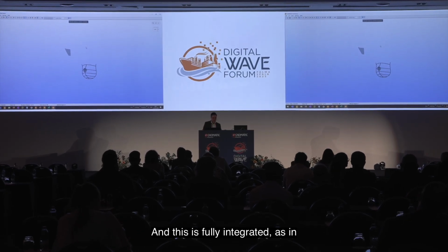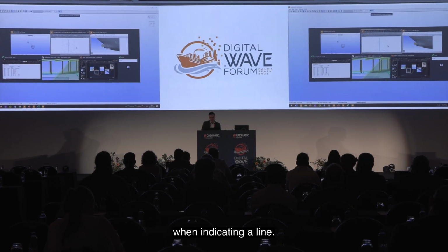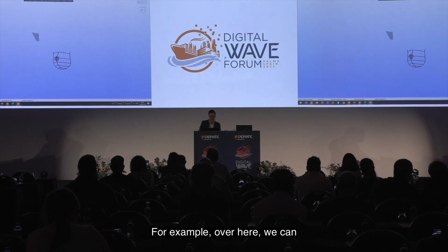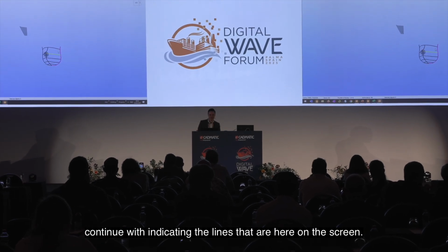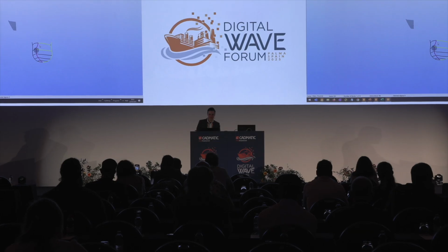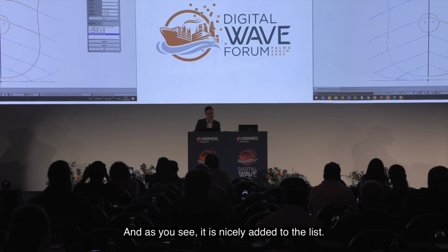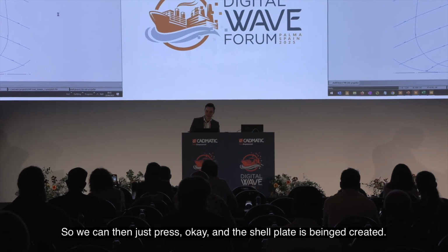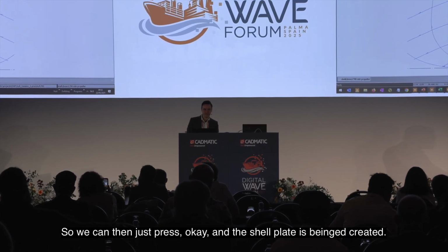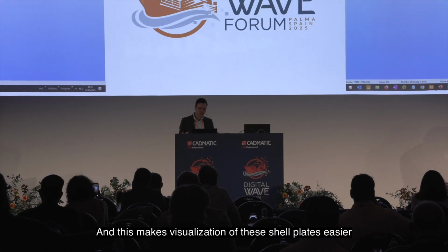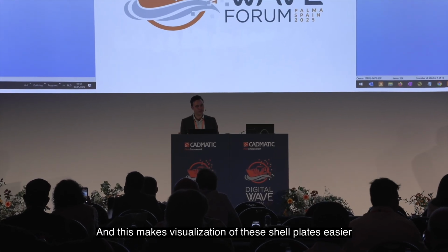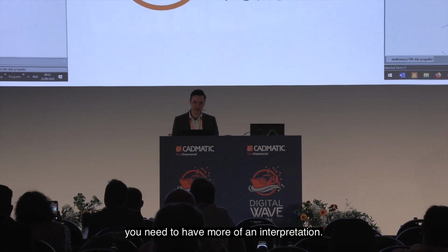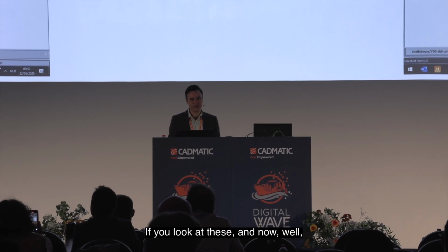And this is fully integrated, as in, when indicating a line, for example over here, we can continue with indicating the lines that are here on the screen. And as you see, it is nicely added to the list. So we can then just press OK, and the shell plate is being created. You don't have to think about this. And this makes visualization of these shell plates easier. It's always three-dimensional, of course, but you need to have more of an interpretation if you look at these.